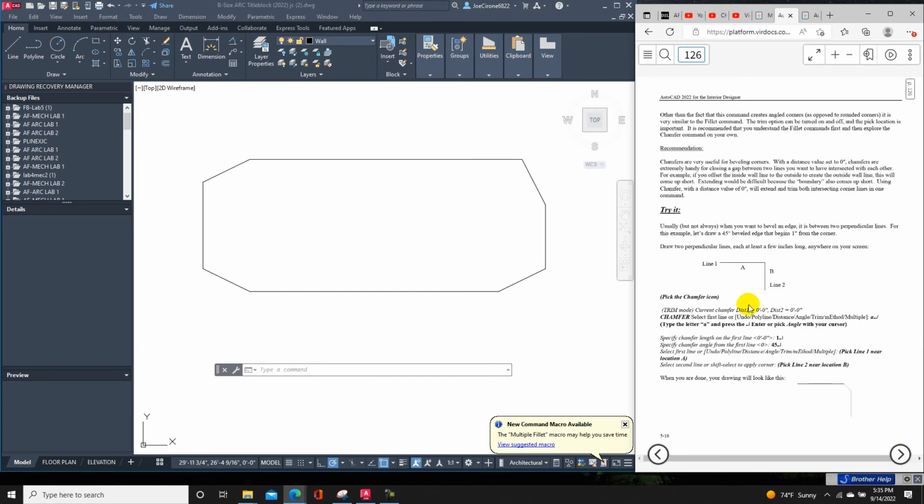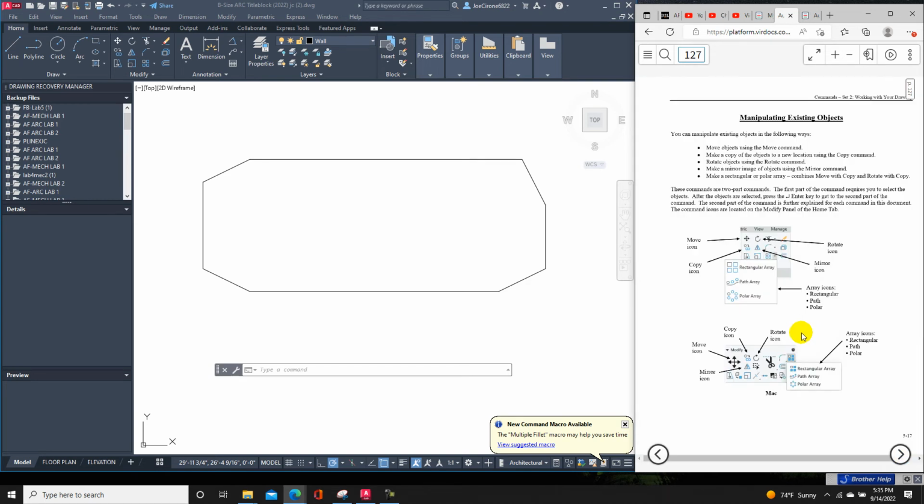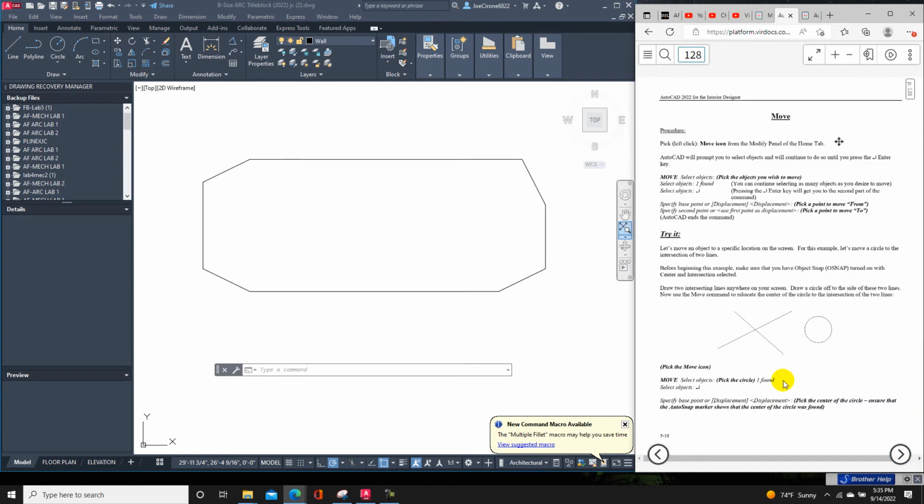And then as we continue on, they just go through some more examples, a lot of words to do something visually very simple. They're looking at using the move command here, the rotate command. And so the rotate command is this little circle with an arrow on it, and basically we're going to look at modify commands. So they're looking at these modify commands over here. You have move, rotate, there's trim, copy, mirror. We're just using the fillet command, and we'll use the array command as well. So let's go through and do a demonstration on that.